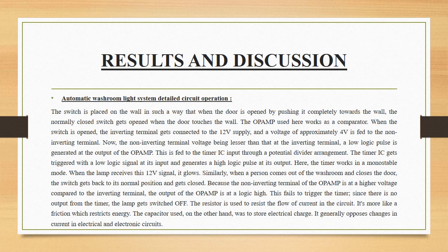Similarly, when a person comes out of the washroom and closes the door, the switch gets back to its normal position and gets closed, because the non-inverting terminal of the op-amp is at a higher voltage compared to the inverting terminal. The output of the op-amp is at logic high. This fails to trigger the timer. Since there is no output from the timer, the lamp gets switched off.